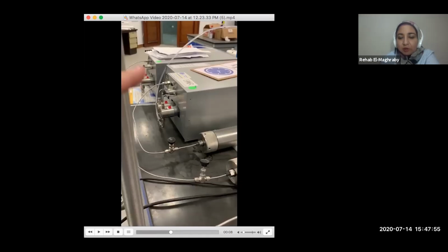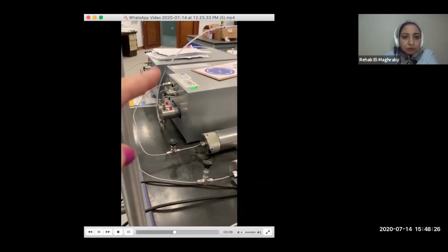And your accumulator has a floating piston inside. One side will be deionized water. The other will be brine or oil or gas, and then you will use the pump to inject your other fluid into the core holder, and they are not in contact. So the deionized water is not contacting the oil or the gas or whatever. And it is actually also a nice accumulator from DCI.